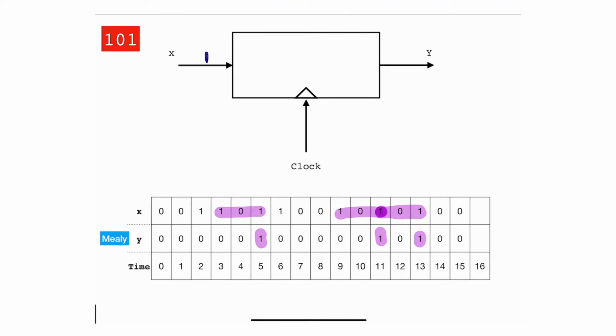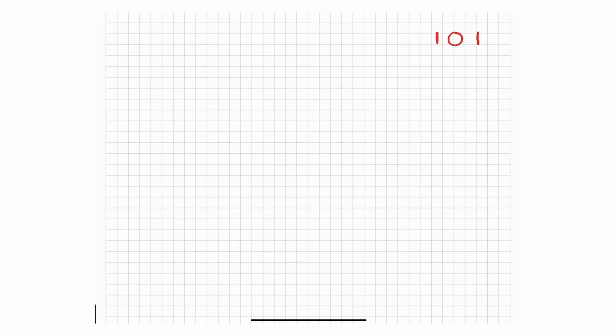So let's get started and design that particular circuit, that particular finite state machine that will implement this sequence detector. Usually the very first step I do is I say, okay, this is the sequence I'm looking for. And I will start by saying I will have some sort of a reset state. I will call it S0, and that's basically the very first state.